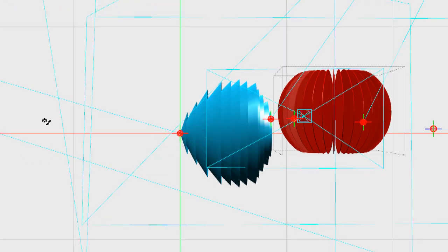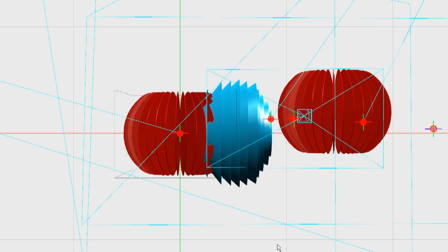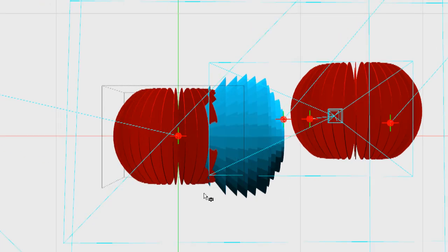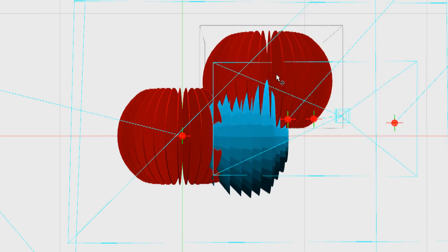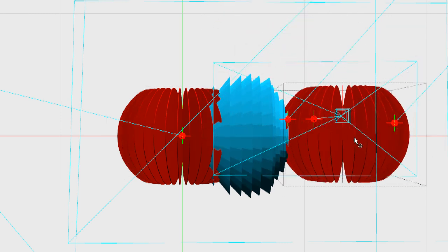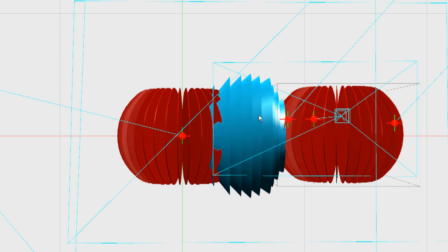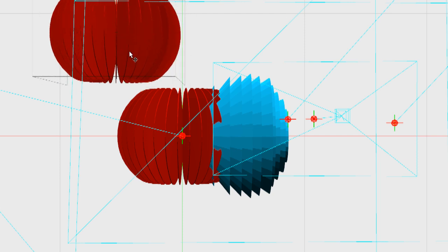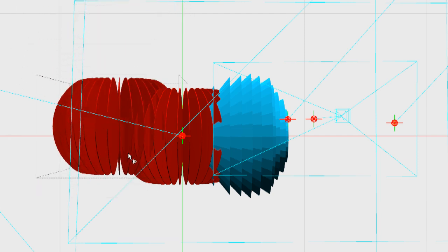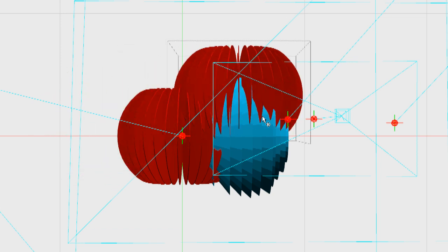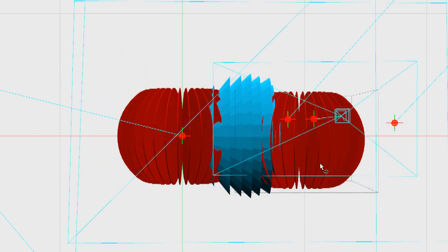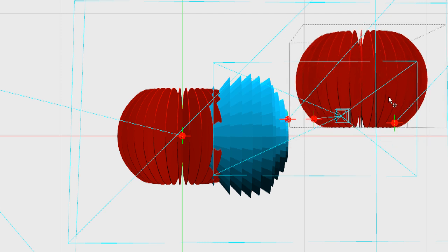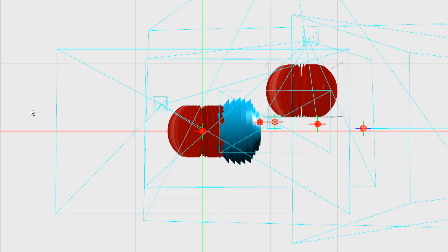So, if we compare the range, which is always an important factor, this is your rubber ducky, and again we would only get to about here, but with the circularly polarized we're going to get a little bit further out because we're 8 decibel versus 2. But obviously the same problem exists. With the rubber ducky we can fly behind and we're all good, or we can fly in front, only in the field of view of a circularly polarized. So let's turn off the ground station